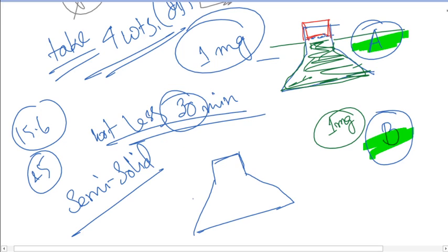So for bitumen we need to raise the temperature. If we raise the temperature, it will become fluid-like and the viscosity will be lowered, so that we can pour this liquid bituminous material into the pycnometer and cool it down to settle into its solid form. Then we can take the weight at 25 degrees centigrade. But before that we need to raise the temperature of this bituminous material.